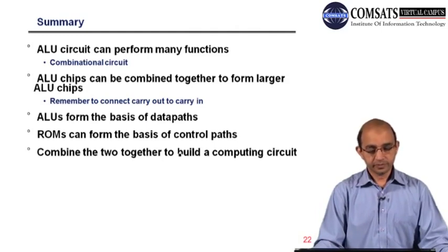We will be deploying only the minterms that are required for a particular configuration. And we performed and showed the simplification, how we achieve it, and after the simplification how we convert those Boolean functions into the real PLA.